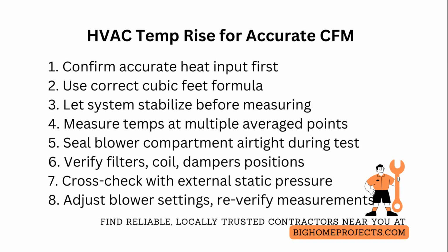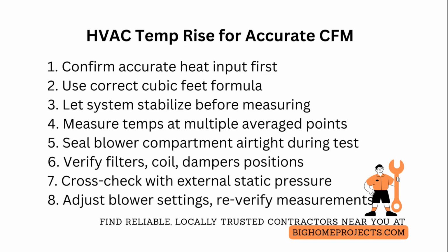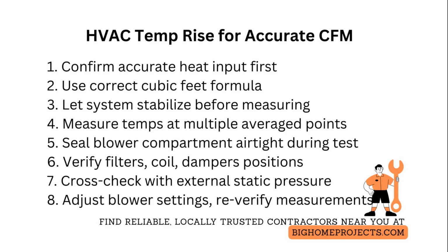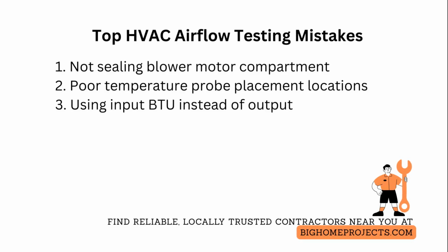If you need to target a specific airflow for heating or cooling, adjust blower tap or variable speed settings, then remeasure temperature rise and static pressure to confirm the new cubic feet per minute, and that temperature rise remains within manufacturer specs.